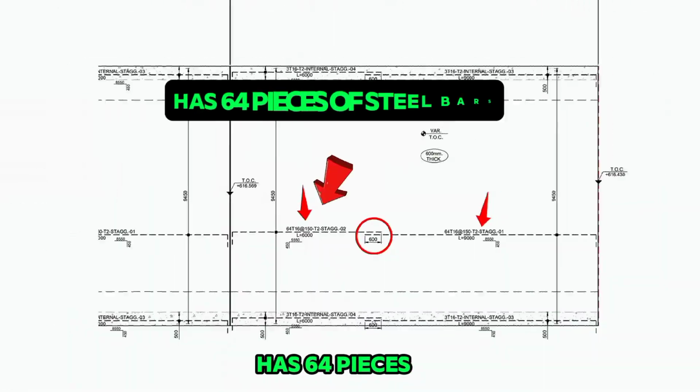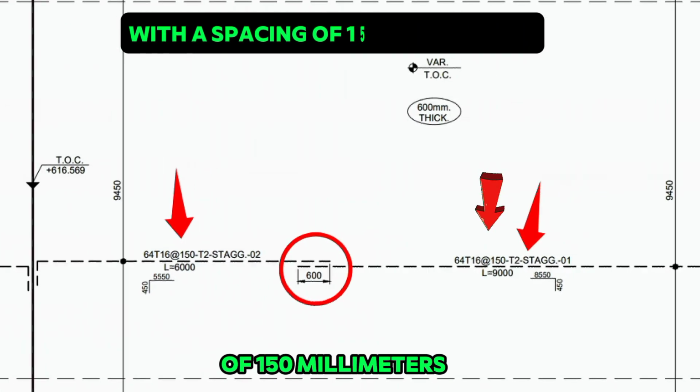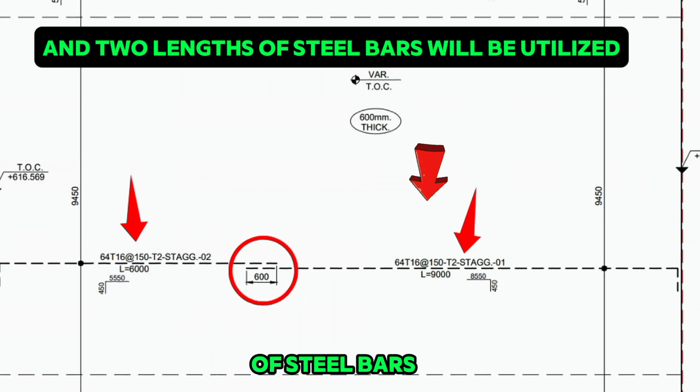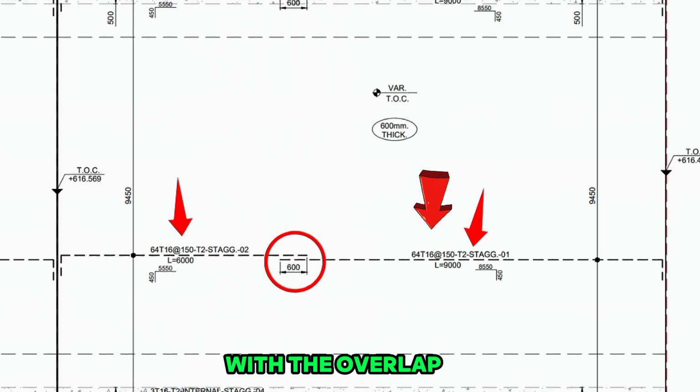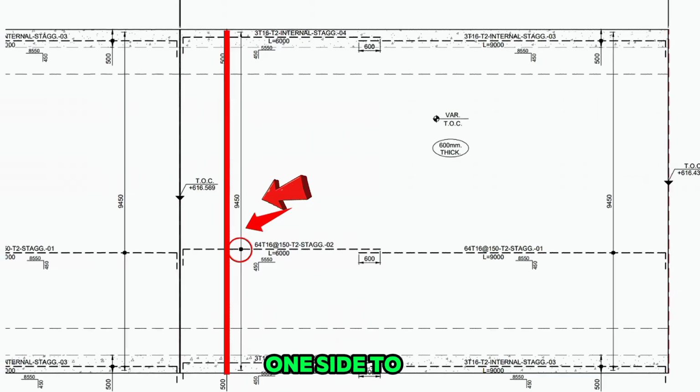The tunnel top slab segment one top reinforcement plan in the X direction has 64 pieces of steel bars with a spacing of 150 millimeters. T2 staggered bars will be used, and 2 lengths of steel bars will be utilized, with the overlap occurring between the slabs. This steel will be provided from one side to the other side.